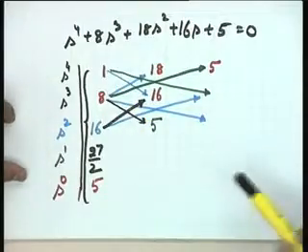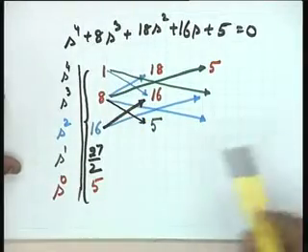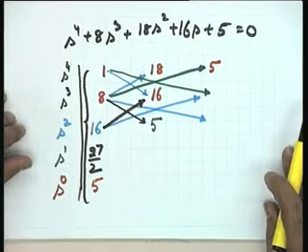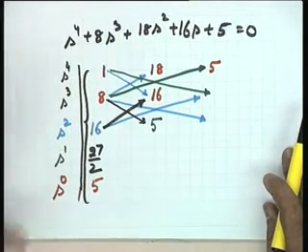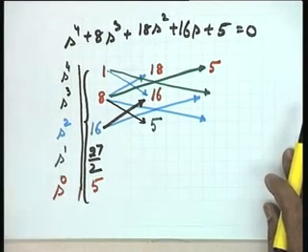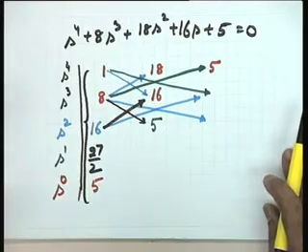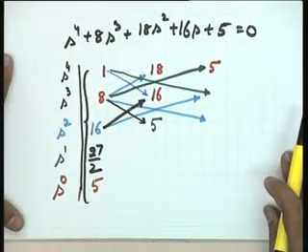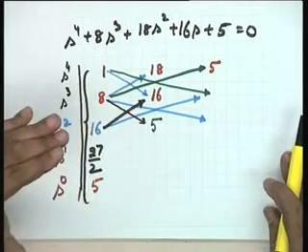Here the Routh array gives you an answer on absolute stability looking at the first column. If there is no sign change, in that particular case the system is absolutely stable, there are no poles in the right half plane. Now, though in this particular case the system is declared to be stable, let us see the other part of the Routh stability criterion.